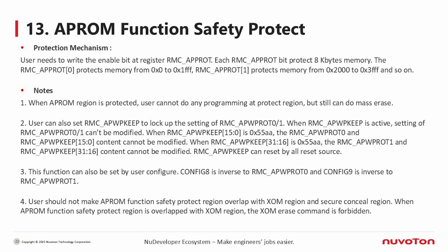4. User should not make APROM function safety protect region overlap with XOM region and secure conceal region. When APROM function safety protect region is overlapped with XOM region, the XOM erase command is forbidden.